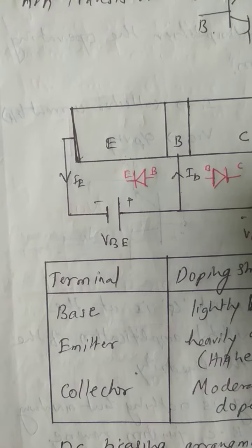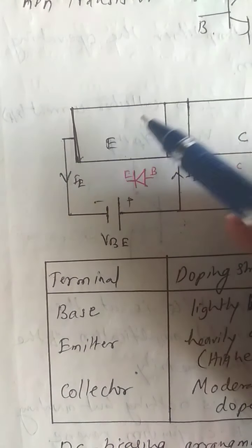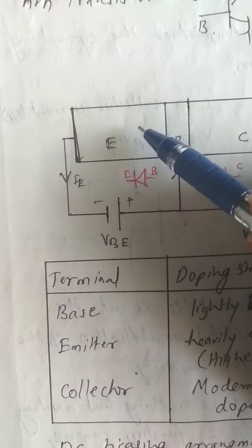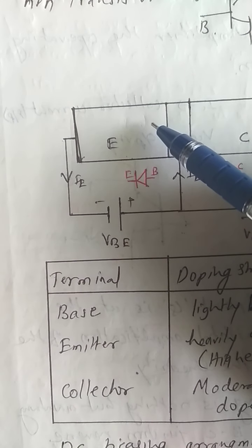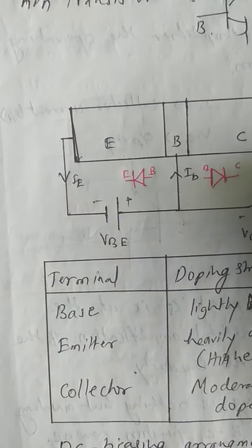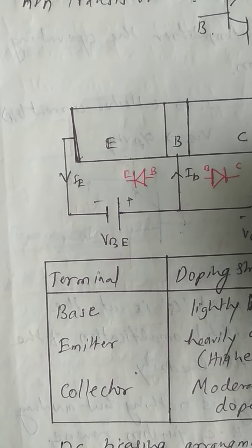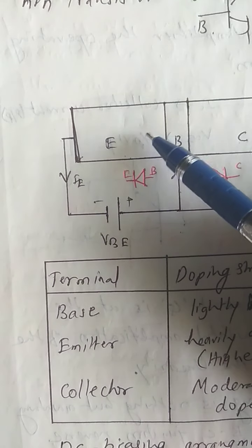The more positive force applied at the collector region will draw the electrons and create holes, and therefore the excited electrons from the emitter will jump into the collector, forming the current in this region. We call that the collector current. So the collector current is going to be a larger current because it comes from these extra electrons, which are larger in number.